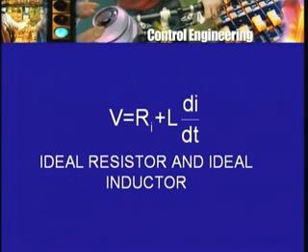And so write down an equation like V for the voltage as not L dI/dt only, but as consisting of two terms, Ri plus L dI/dt, where the term Ri is coming from or taking account of the fact that there is a lot of length of wire there, and the L dI/dt part comes by taking account of the fact that the wire is wound round a magnetic core, current flow gives rise to magnetic flux, and change in magnetic flux leads to the phenomenon of a counter EMF or a back EMF in the wire, and so on.